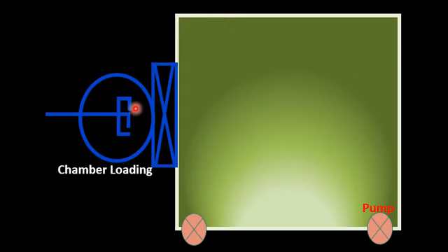Load lock is basically a locking of the precursor material in conjunction with the MBE reactor. Since the vacuum inside the MBE reactor is quite high, it is not possible to introduce the precursor again and again by breaking the vacuum. So the load lock system, or chamber lock system, controls the vacuum.